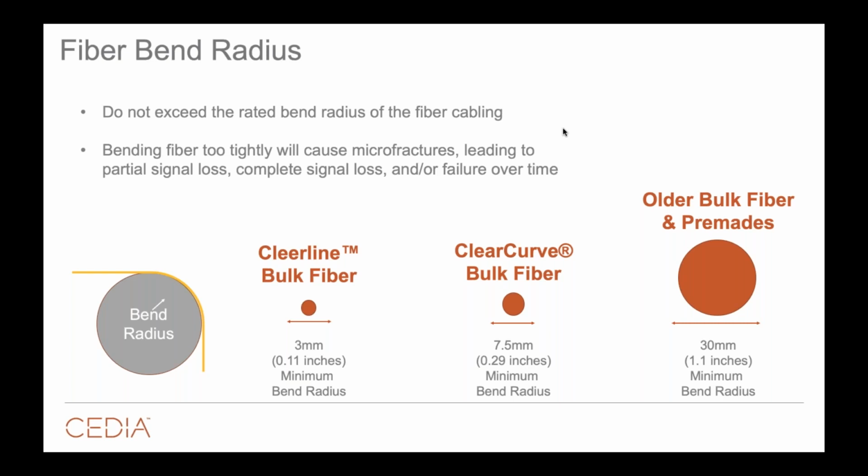In fact, one of the best things that can happen is you handle it rough and you break it and you know you broke it. What tends to happen with older cables is it'll get a crack in it, and then over time it'll slowly degrade. It's a really hard problem to troubleshoot. So you want to make sure you're careful when you're working with a lot of that older fiber optic equipment and cables and things like that.